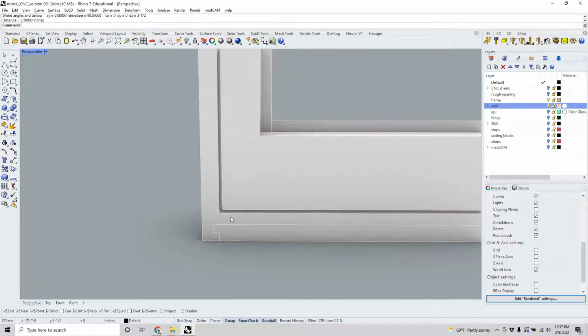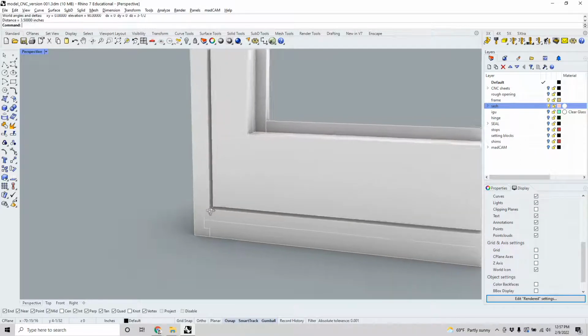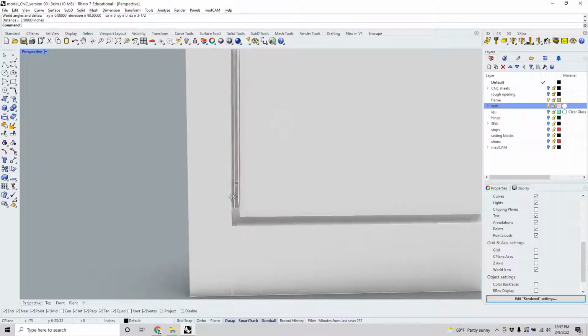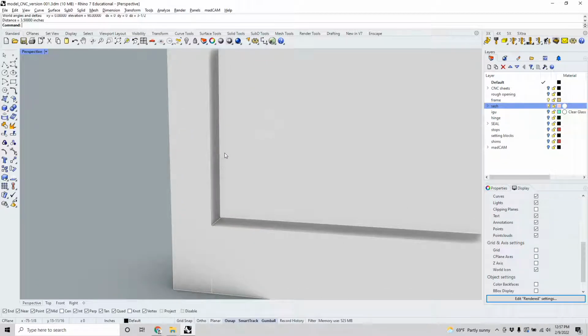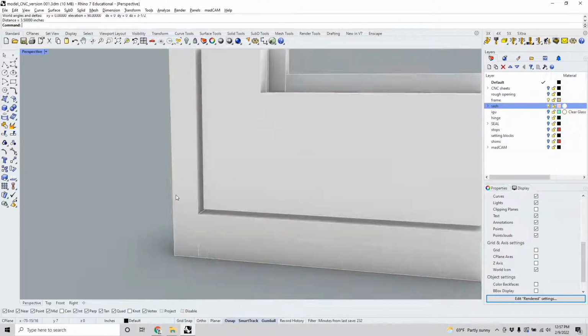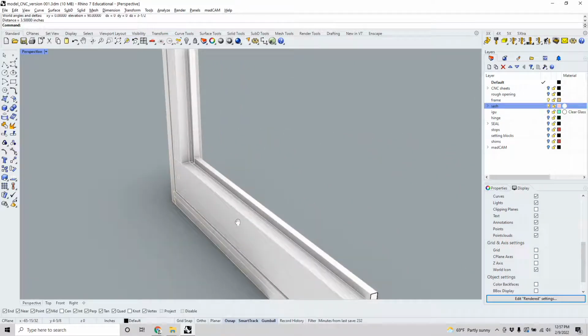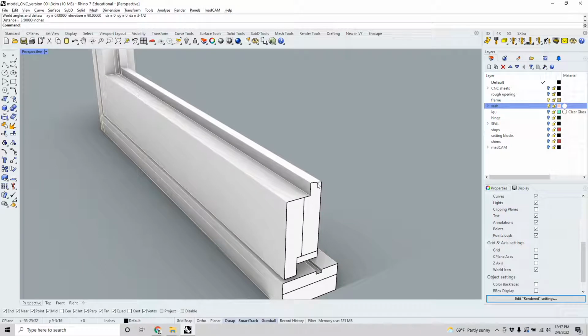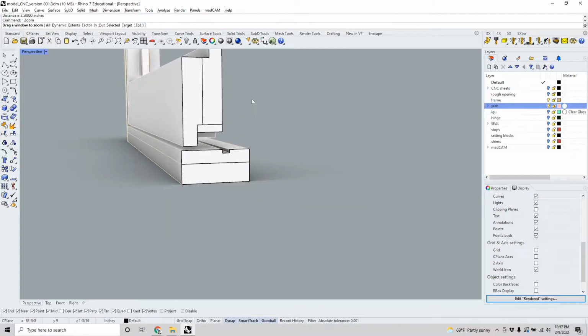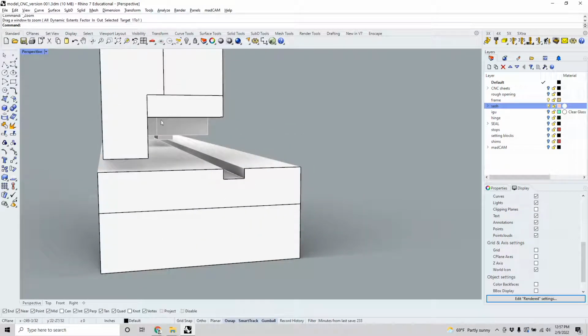And I have a 3/8 gap all the way around the sash and the frame so that they don't bind against each other. And on the hinge side, which is not this side, but the other side, well, it could be either side, but in this model, it's on the right side. This side is chamfered, or you can radius it so that it doesn't catch against the frame. The outer half of the sash has a rebate built in to accept the glass. And this pocket down here is meant to hold the friction casement hinge.